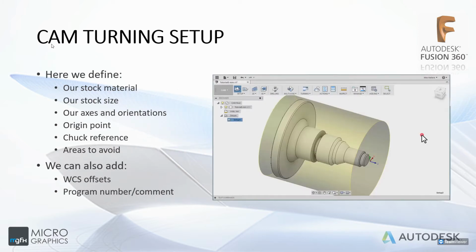Okay. The first thing we're going to discuss of those three steps is the CAM turning setup. Here we will define our stock material, our stock size, our axes and orientations, our origin point, the chuck reference, and the areas to avoid.